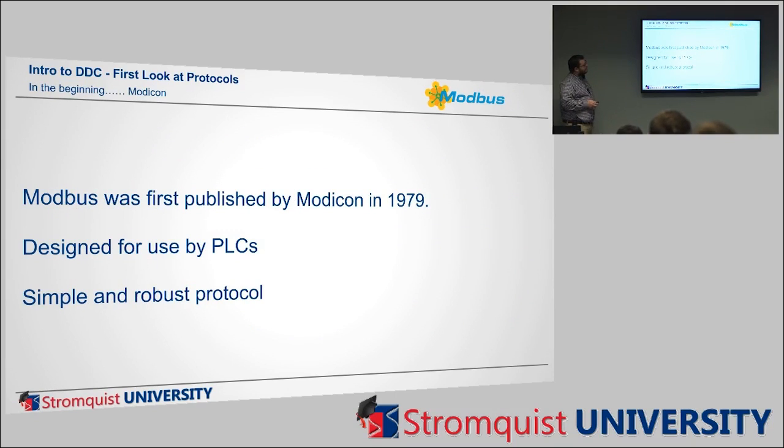All right, so I put Modbus on here because you're all going to run into it. Modbus was first developed by Modicon in 1979. It's been around forever. It was designed for a way for their PLCs to talk to each other. It's a very simple protocol. Doesn't have a whole lot of features. I can't go to a Modbus network and hit discover and it polls to see how many devices I have out there. I can do that with a BACnet or a LON. Modbus is very simple. You've got to manually do everything, but it's really robust. Since it's so simple, there's nothing really to break on it.